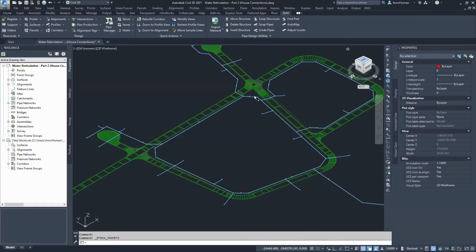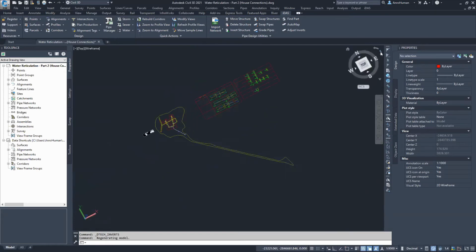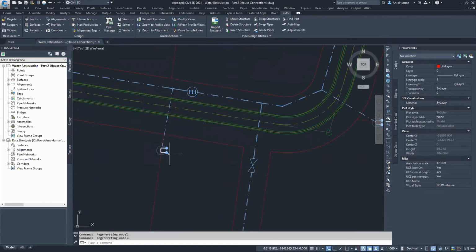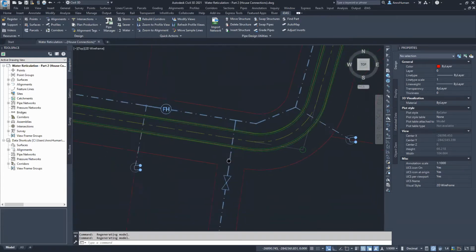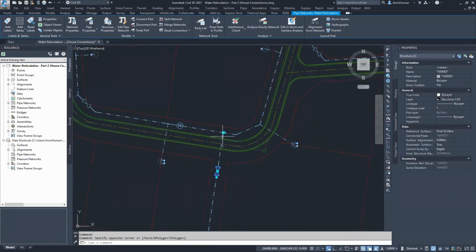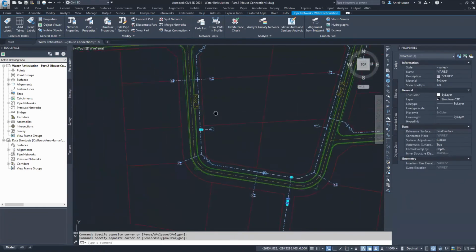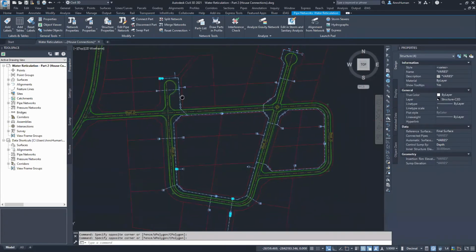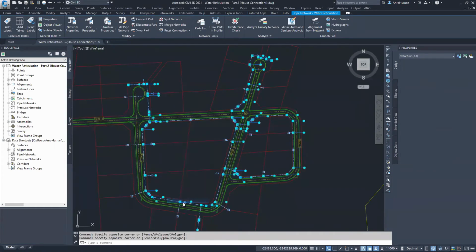I want to make it so that all of those parts are in line with our pipes. So our house connections can be at ground level. Our fire hydrants can be at ground level because those need to stretch up there, but all of our gate valves, as well as all of our junctions, our saddles and our end caps, can't stretch to the ground because that's just not how those structures work. So I'm selecting one of each, and I'm going to right click and select similar.